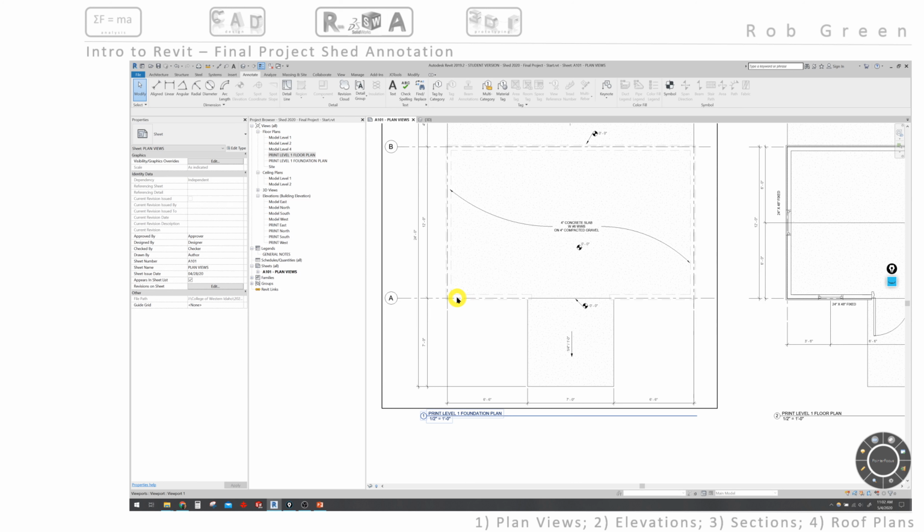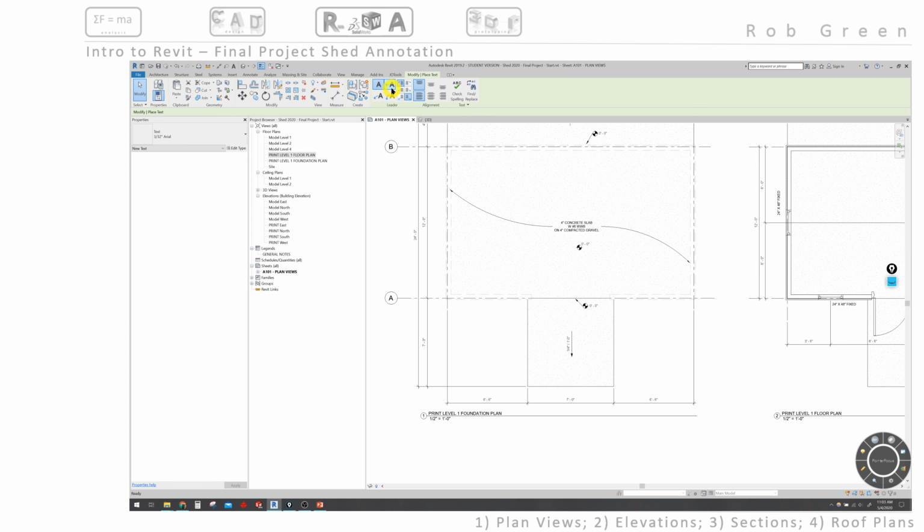In the foundation plan, I'm showing the walls at a very low resolution. I think we talked about that. And as dashed lines in gray. Although, because it's a foundation plan, walls really shouldn't show. And because I'm showing them, I need to tell whoever is reading the drawing why they're showing. So I'm going to put some text in here explaining that.